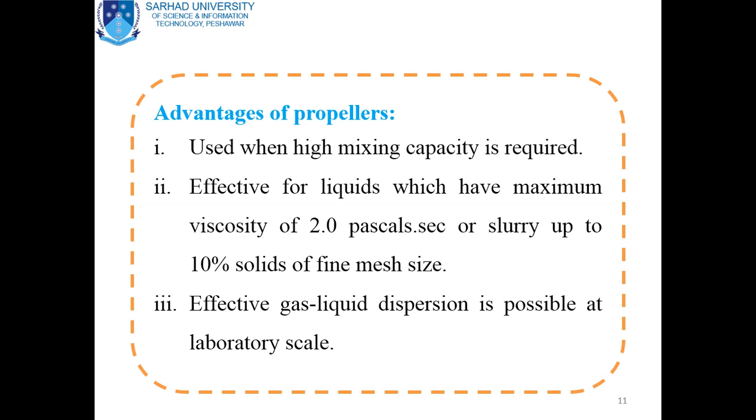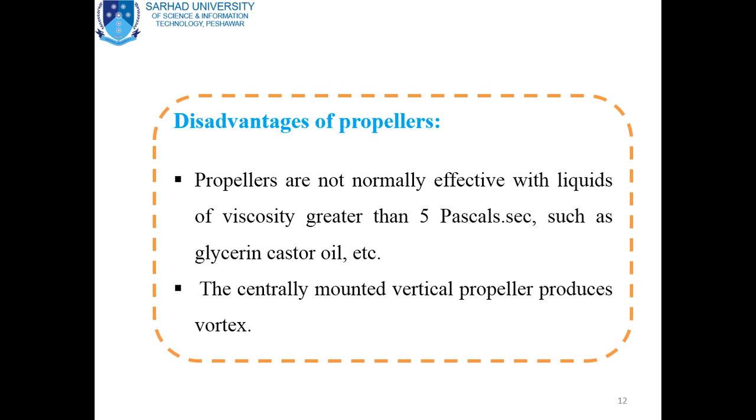If we are interested to disperse gas into liquid, it is possible by using propellers at small scale. There are certain disadvantages, including that propellers are not normally efficiently used with liquid of viscosity greater than 5 Pascal second, such as glycerine, castor oil.